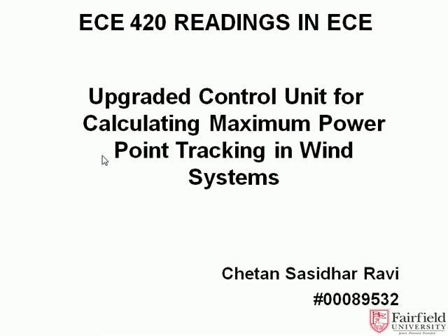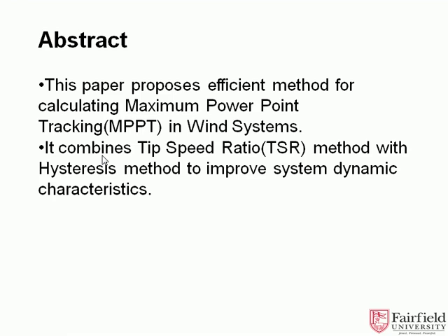My thesis proposal is on calculating maximum power point tracking. This paper presents an efficient method to calculate maximum power point tracking. Usually the present systems run on TSR method control, and I'm combining this TSR method with hysteresis, which improves the dynamic characteristics of the complete system.